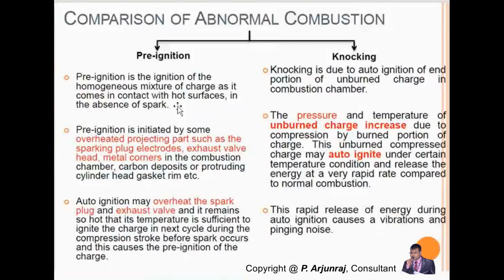And again, this pre-ignition can be initiated by overheating a projecting part. You need to overheat the electrode of the spark plug, the exhaust valve, or metal corners. What happens with pre-ignition is that when you overheat the spark plug and the valve, the temperature remains high on the surface, which is sufficient to ignite the air-fuel mixture itself. And even if you're not producing the spark,